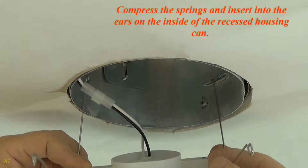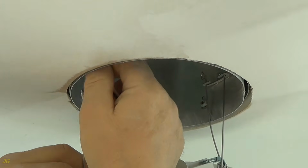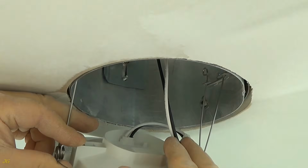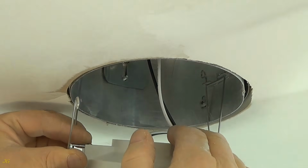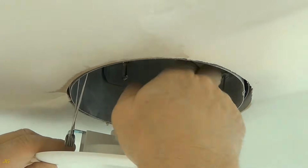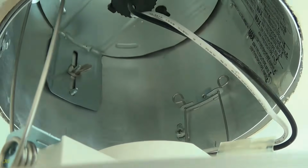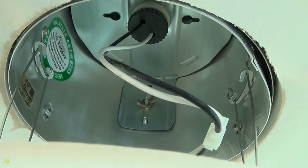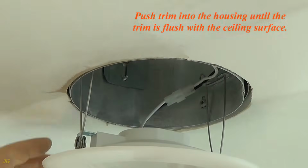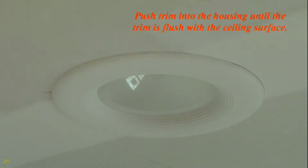Compress the springs and insert into the ears on the inside of the recessed housing can. Push trim into the housing until the trim is flush with the ceiling surface.